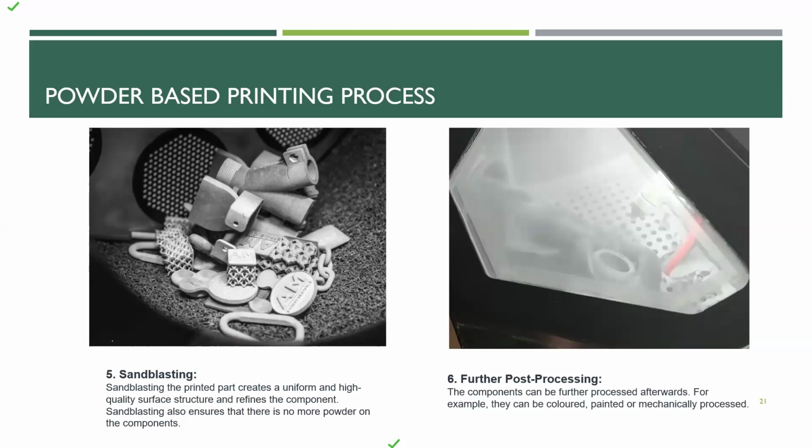Just you have, and why it is the preferred method for metals, is that it does not have sintering in it. You don't have to heat the metal to become a liquid and then convert it into a shape in the form of molds. You just have to have a powder material, powder metal, and you apply the binder on top, any shape which you want, and the binder will form the shape.